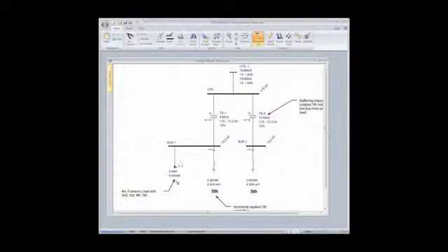But over here, instead of putting a 6-pulse drive that the fifth harmonic filter would obviously work well with, I put an arc furnace load that could be characteristic of any number of types of arcing loads, which have a rather random or stochastic process in how they produce harmonic currents. In this case, this is an actual arc furnace in a melting condition with second, third, fourth, and fifth harmonic.